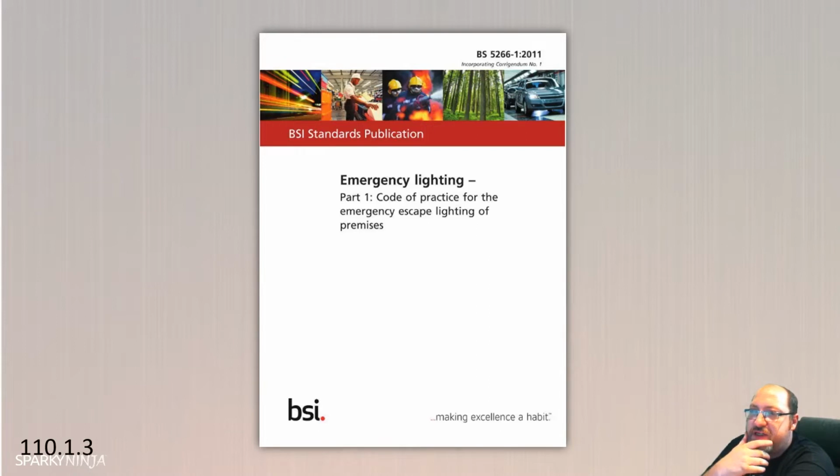It will tell us that the wiring system shall not go through an area that's exposed to explosions, but should also not go through a fire area. It'll also tell us that there's a classification, so a change over time: medium break, no break, very short break. It'll also tell us that there are sources of safety services, primary cells, batteries, and things like that.